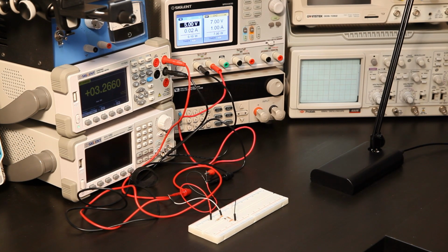And then I've got the Zener diode, which needs 20 milliamps for IZT. So with 20 milliamps and 3, that's 23 milliamps. And with a 5 volt supply, there's a 1.7 volt drop across that series resistor. And 68 ohms gives us about 23 milliamps. Actually, it was 72, but I opted for the 68 ohm resistor since it was close enough.